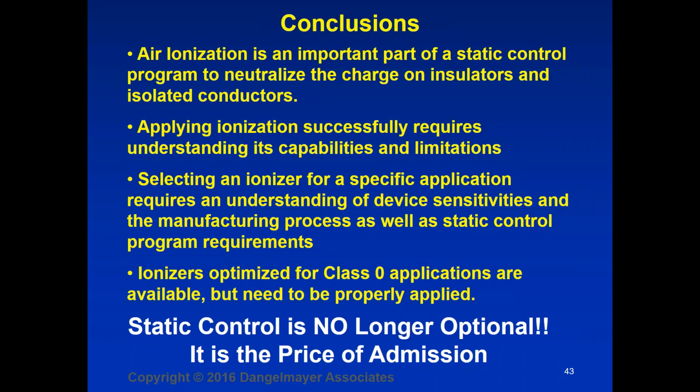Is the test method to test ionized air guns the same as benchtop ionizers? Pretty much the same. If you look in STM 3.1, there is a procedure in there for testing blow-off guns and nozzles, and typically, if it's just an evaluation, you're going to hold the blow-off gun approximately 6 inches from the isolated plate. The isolated plate is going to be located 6 inches from ground, and you're going to charge the plate and then aim the gun at the plate and measure the neutralization time. So the answer is yes, it's pretty much the same as you test for benchtop blowers.